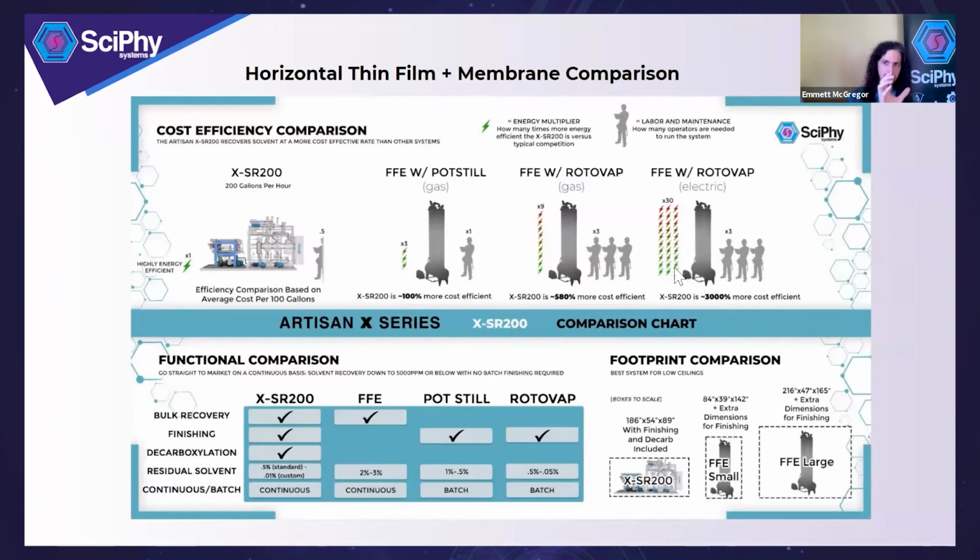You're combining a continuous type solvent recovery system in the falling film with a batch finishing step. And when you do that, your rotovap requires tending. It is a manual operation of loading it and unloading it typically, especially when you're going to these large 50-liter type vessels. You're talking about a lot of manual input of labor of taking that bulb off, putting the bulbs back on.